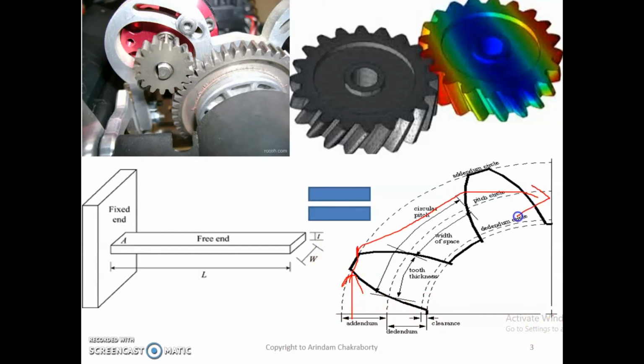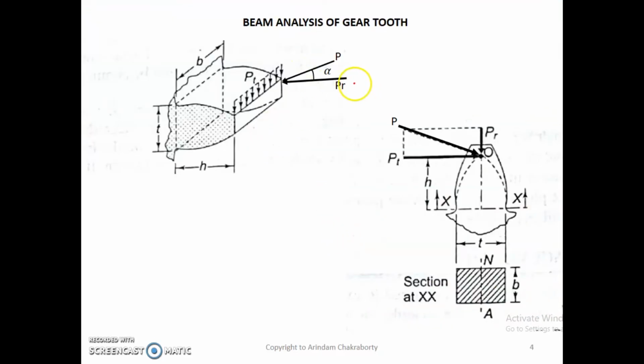If you apply a force this way, this force will be transferred over here, that means it will not create any rotational motion, hence there will be no transfer of motion from gear 1 to gear 2. So that's why I have neglected this force as stated over here, because it is directed inwards towards the axis.